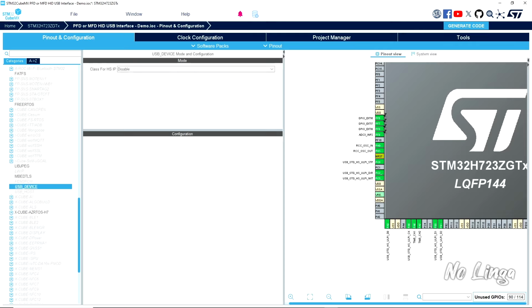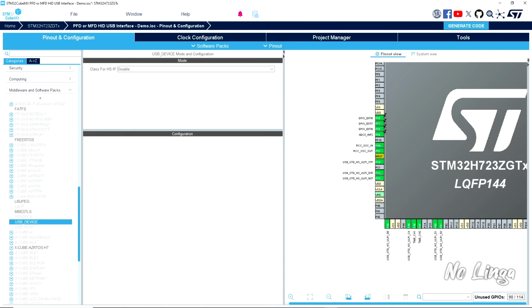There's something here that looks a little bit strange because I didn't need to have the additional pins. Because we didn't select OTG, and that's one of the things that happens with this configuration tool. It will give you a kind of configuration. While it wasn't showing up on my other configurations, it will sometimes show up here. So that's what I'm just making sure.